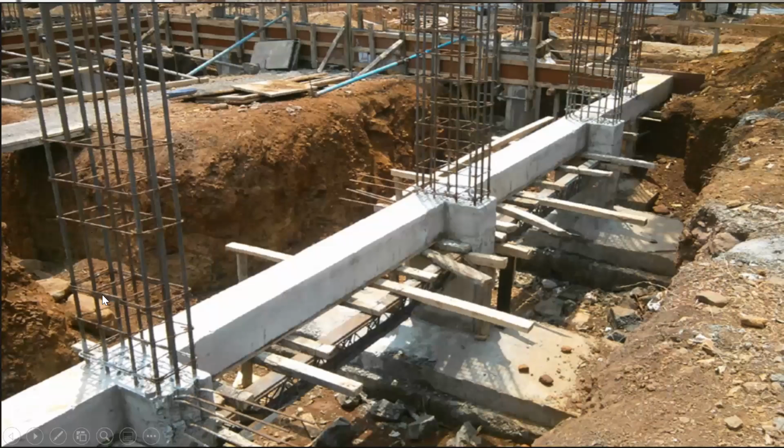Again, if you observe, there's one ring which connects all the longitudinal rebar. Then there is one more lateral tie which is connected at this point, right? This is one which goes completely. Then there is one more which is going to connect only the middle 4 bars, right? So everywhere, and the spacing they have mentioned is 150 center to center, 150 center to center, 150 center to center. Based on the drawing, we are going to provide this.